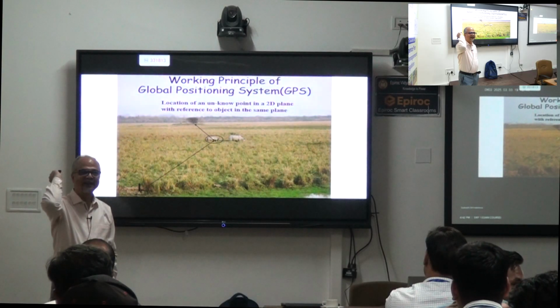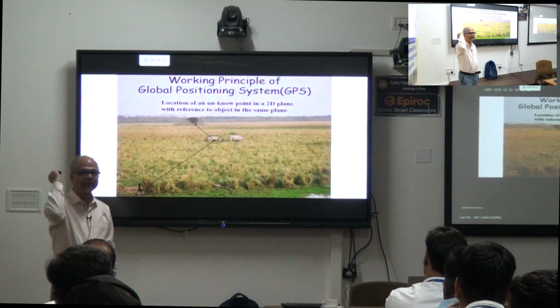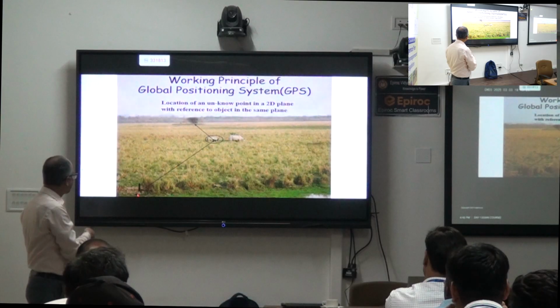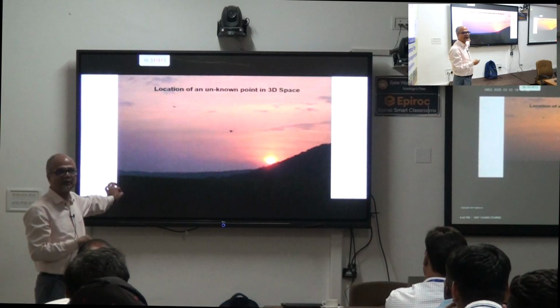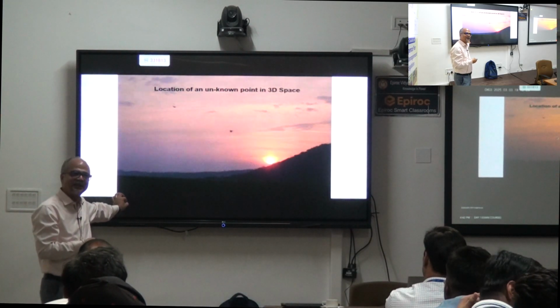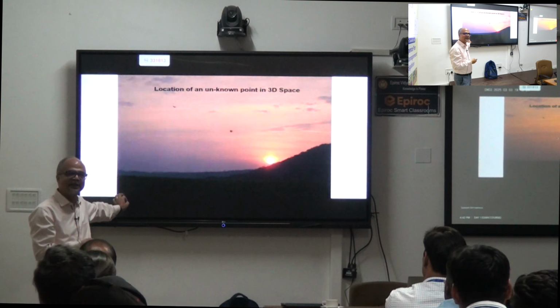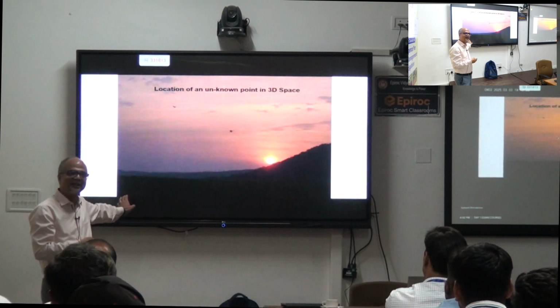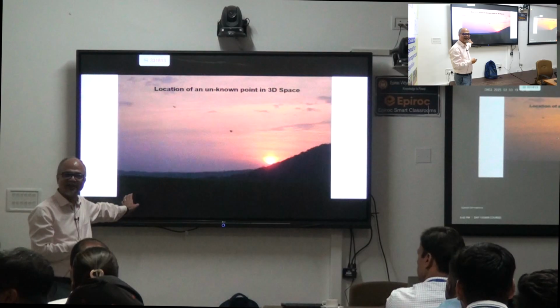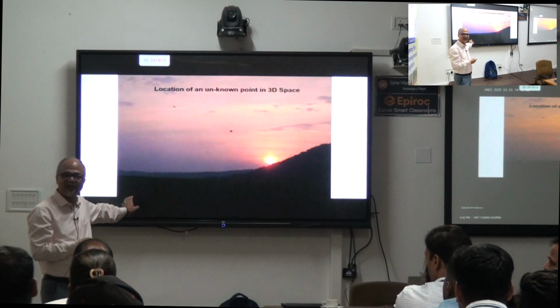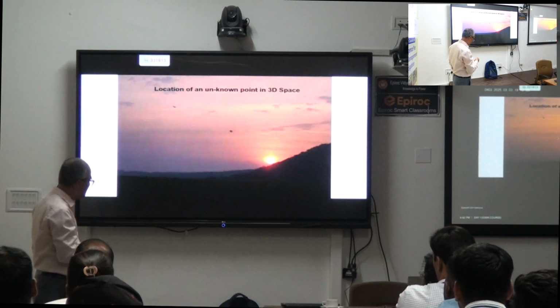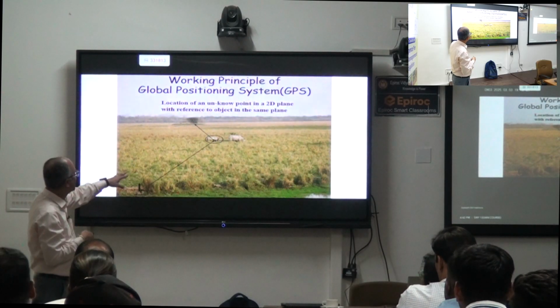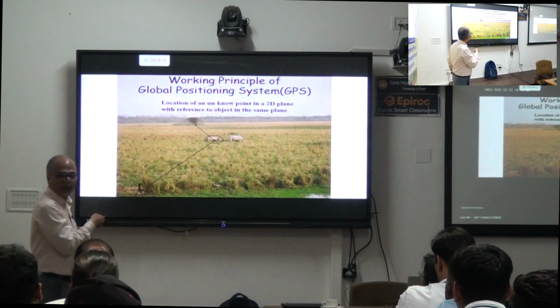It will require the coordinates of the pillar. Suppose the coordinates of this pillar I consider as fixed, then is it sufficient? No, sir. Still no. Why? Sir, one of the benchmarks is moving. If one of the benchmarks is moving, it means this is also moving.